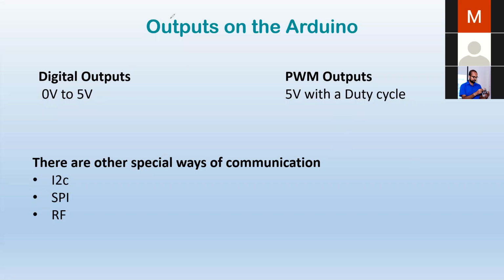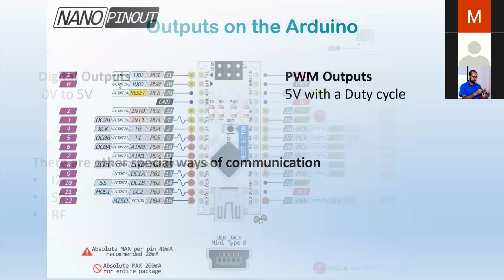If you do polling, that is digitalRead, that is a polling technique. We call that polling because for each cycle of the void loop, we check what is happening with that condition. So with polling, you are going to waste system memory and system speed, but with interrupts, you are not going to do that. If you get an interrupt, if you hear the ringtone, there is a thing you want to do, right? Like answering the phone in the cell phone analogy, in a microcontroller you might need to do something. That is what we call the ISR, interrupt service routine. Don't mind these things; I'm just giving you the background knowledge, so these words don't take you by surprise when you do the practicals.